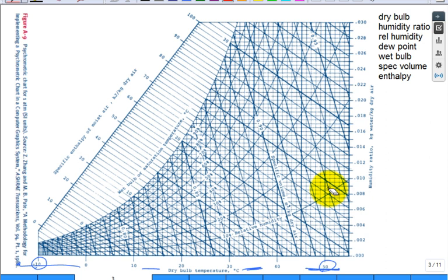Okay. Now, what about the y-axis? Most of the time they put the y-axis on the left, but there's nothing to say you can't put it on the right. True? Yeah, so they put it on the right side. The y-axis is my humidity ratio, my omega. Look at the units: kilograms of water per kilogram of dry air. They remind us, good, just like the degree C for the dry bulb.